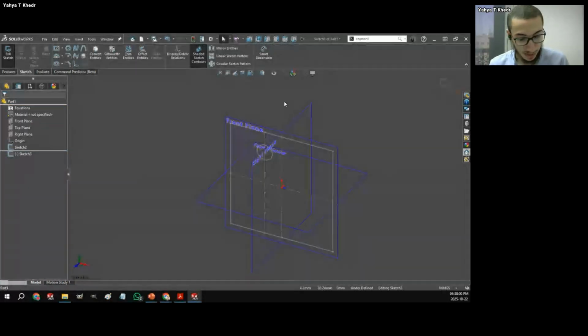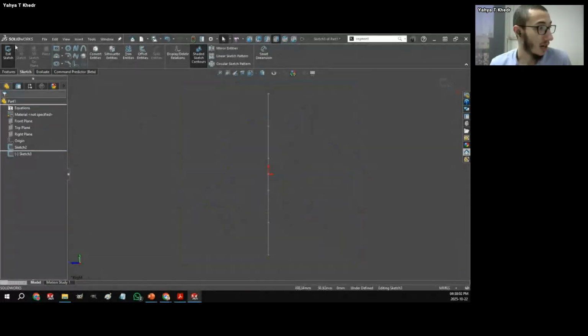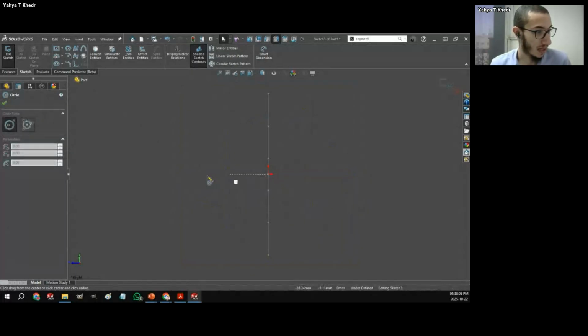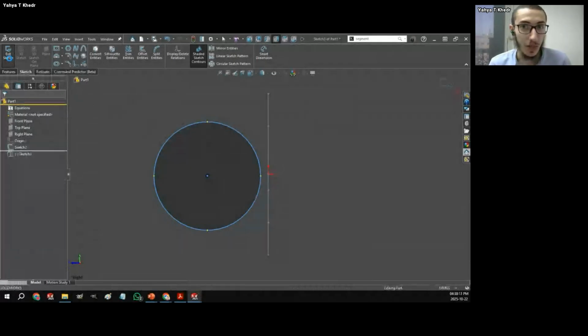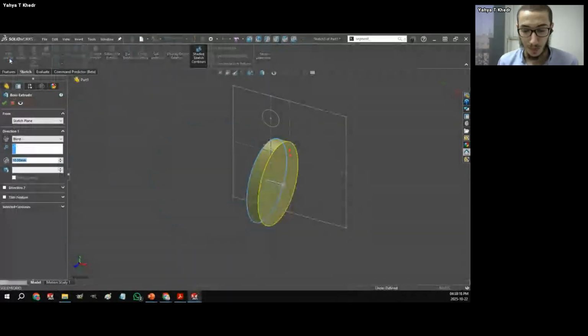So right now I'm inside of the sketch mode, right? I'm in a sketch. I can do anything, maybe like a circle over here. Okay. And now when I exit the sketch, notice I'm going to click exit sketch, but it remembers that I came from the boss extrusion. So it's now going to take me back again to the boss extrusion. Okay, Tanvir, is it now a bit more obvious that you don't have to do multiple clicks? It's all about knowing how the software works and taking that into consideration while you're going ahead.